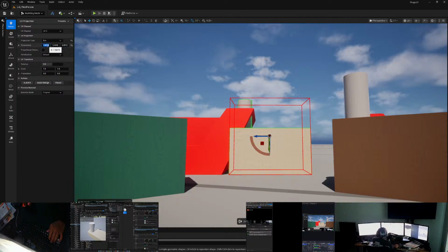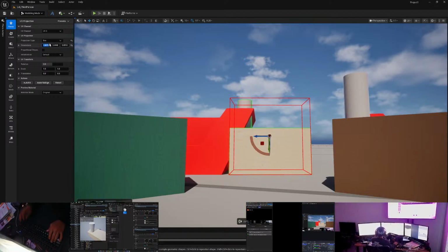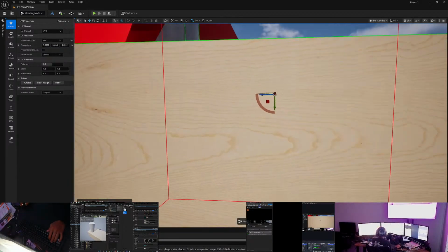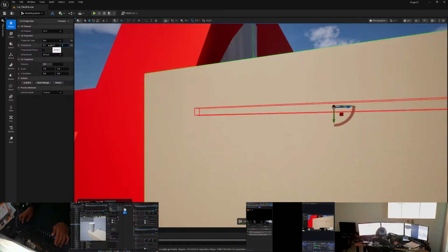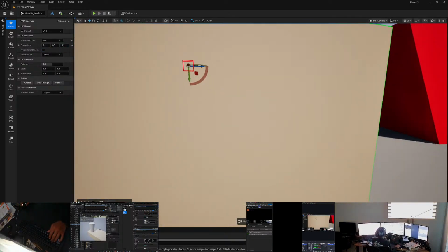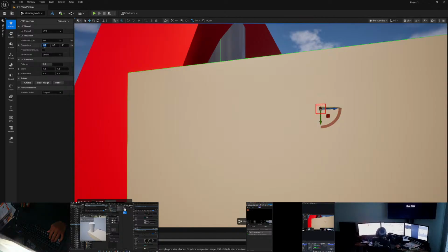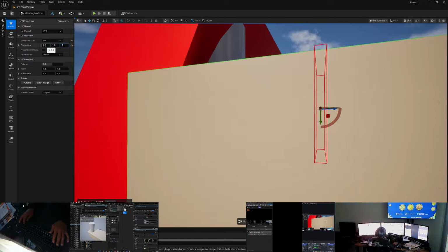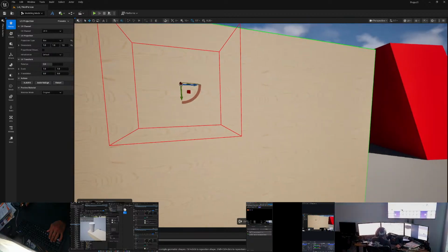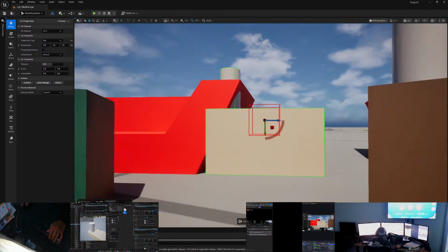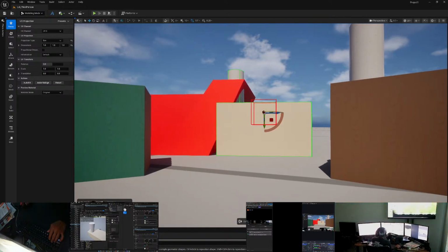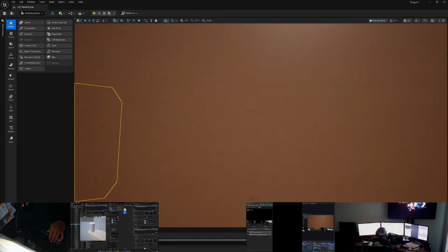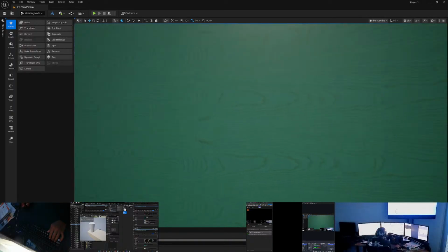and then I can set the dimensions to, let me zoom into it real quick. Let's say I want it to be really small, so 0.1 tab, 0.1 tab, 0.1 tab. That's extremely small. So maybe let's see what 1 looks like. 1, 1, 1. It's a seamless material. That looks all right. Zoom back out. Let's hit apply or accept. And you can see that the UVs for these also changed.